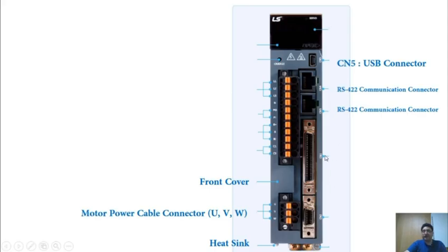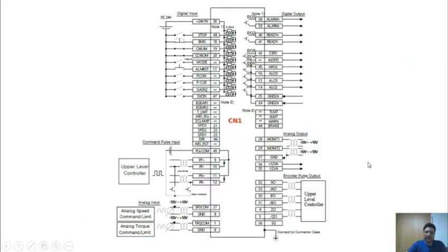The HMI is a device that provides a way for people to interact with machines easily. Using the HMI, we are able to both read and modify the internal parameters of the drive, which means we can check the current settings and make changes if necessary, all through a user-friendly interface. Well, the most important part of our servo drive is this CN1 section, which is related to our control signal. This shows us the image of CN1, which is a very important connector.